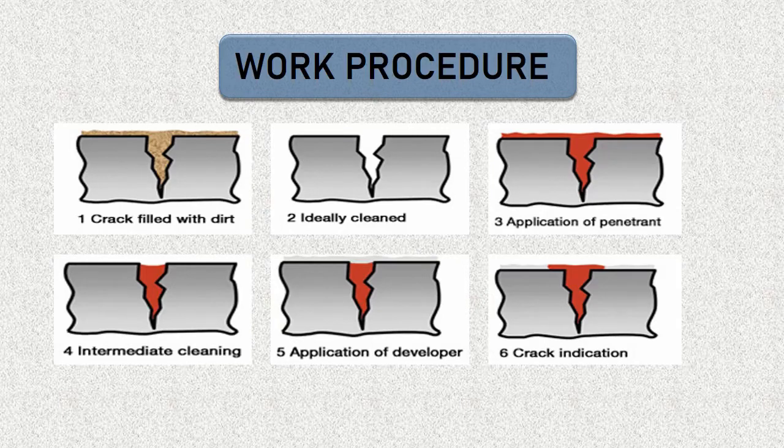Then, excess penetrant removal. The excess penetrant is then removed from the surface. The removal method is controlled by the type of penetrant used: water washable, solvent removal, lipophilic post-emulsifiable, or hydrophilic post-emulsifiable. Then, application of the developer. After excess penetrant has been removed, a white developer is applied to the sample. Several developer types are available, including non-aqueous, wet developer, dry powder, water suspendable, and water soluble.